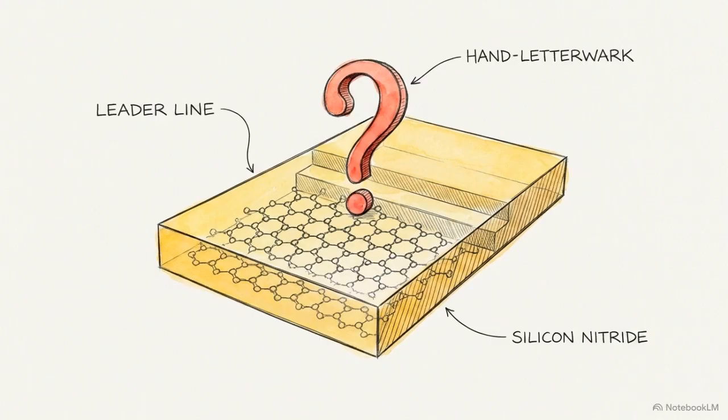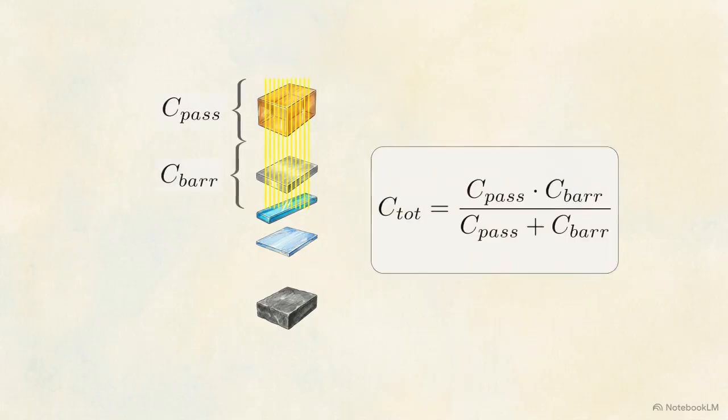Modifying the thickness of a silicon nitride layer in isolation will not yield predictable results. True device optimization requires treating the top dielectric and the underlying epilayers as a single, interdependent electrical system.